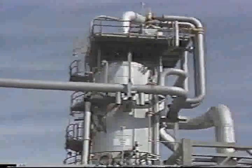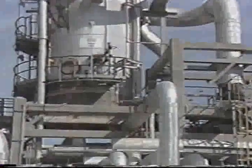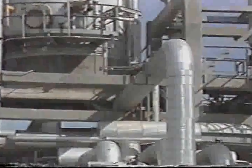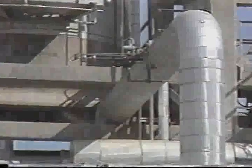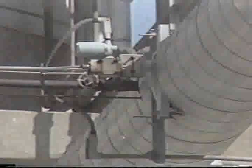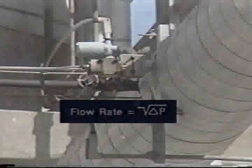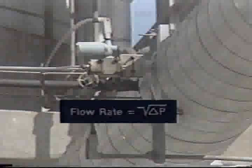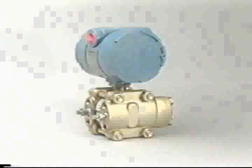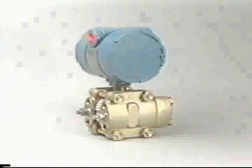Once you understand how an instrument operates, calibration isn't difficult. For example, flow rate is the square root of the calculated pressure drop across a restriction. Differential pressure transmitters may include an integral square root extractor, which converts differential pressure into flow rate. Remember, flow rate is the square root of the calculated pressure drop across a restriction. Integral square root extractors are part of some transmitters.